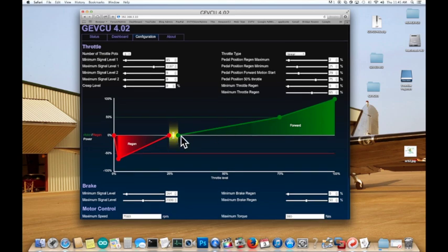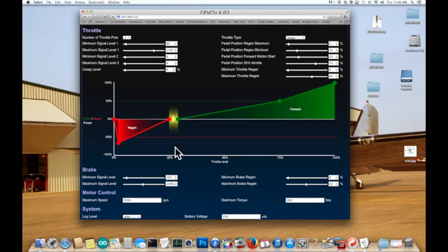We can't really overlap these values, but we can connect them. I've left a little gap here from 25 to 29%. What would that be for? Well, there I get no torque. I don't get regen, and I don't get forward torque. As you can see, this is labeled coast. If I can find that notch, I can just free roll and not use any energy, not make any energy, and the car will just roll on and on. So I like having this little coast notch in there.